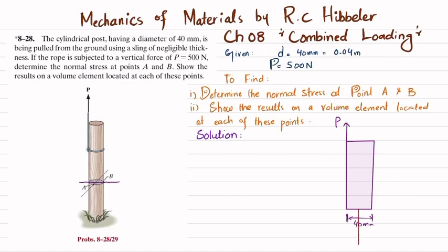this, and let this force be N. There will be a shear force which is V, and there will be a moment as well which is M. So you can see that for finding the shear force, the sum of all forces along the horizontal direction must be equal to 0, and force in this direction is taken as positive. So only V is acting horizontally and there is no other force, so it means that the horizontal shear force is equal to 0.